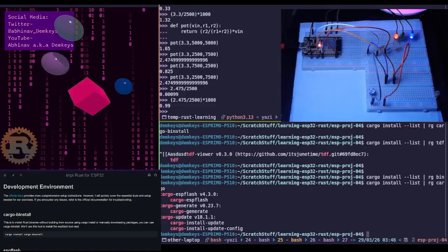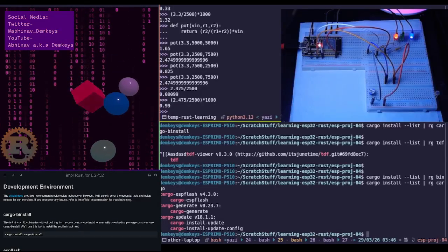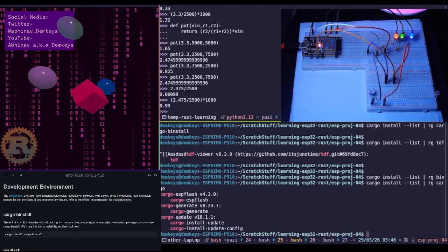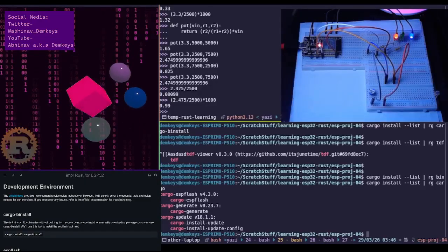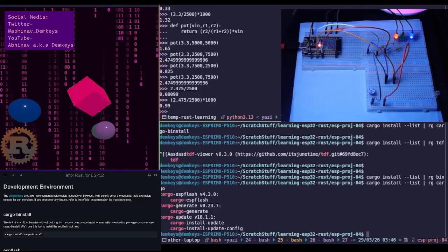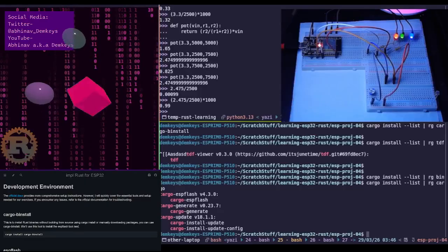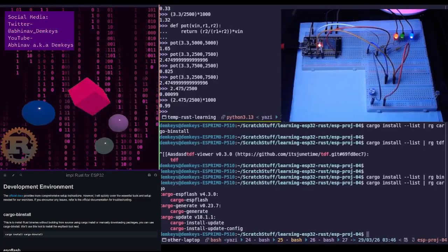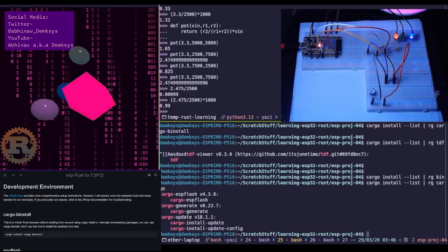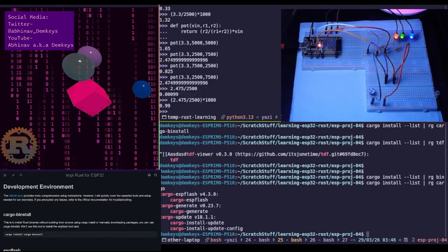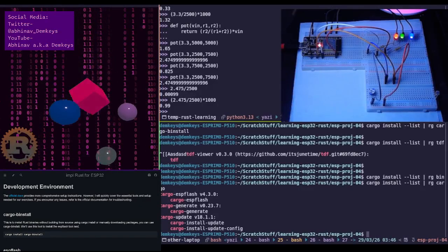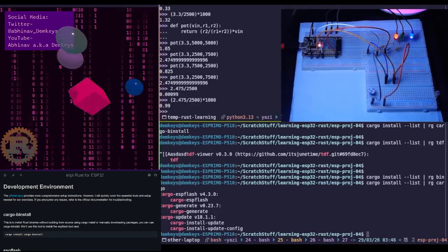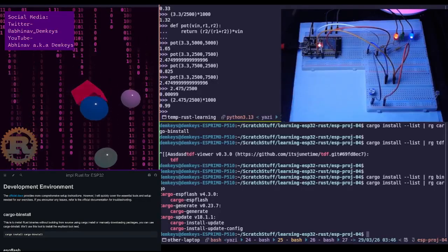You don't directly use the relay because there's a lot of circuitry that has to be built around that. Generally, if you are doing it especially through a microcontroller, you would use a relay module. So the relay is in the module itself. The relay is within that PCB, and there's a bunch of other circuitry there, including pins to allow you to connect a microcontroller in. So a relay module is what you're looking for rather than just a relay.